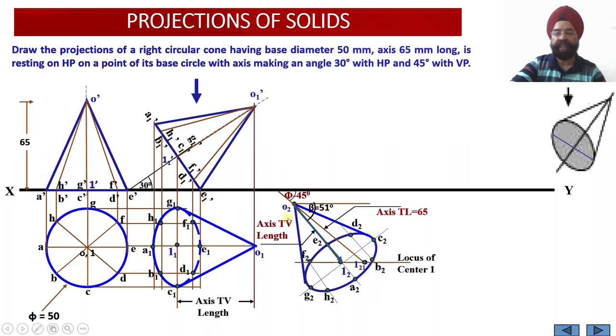So now this plan projection which was obtained in step number 4 has been rotated and translated at an angle of beta equal to 51 degree. Now we have to obtain the front view. So once again corresponding points we are going to work out. So vertical projectors we have to draw from here. Horizontal projectors will be drawn from the previous elevation view. But before we proceed, this line was not dotted because this picture and this picture should be the same. So please check, no dotted lines were there.